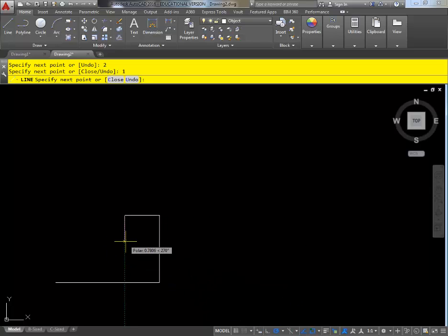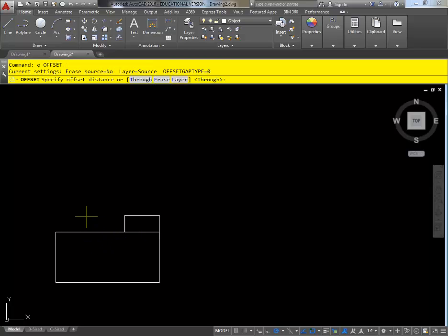And then back down 0.5. Close that. Looks like that should extend. And then I'm going to use an offset of 0.5 to bring that down. So if I'm not mistaken, those 3 rectangular shapes, eventually I'll hit the right button here, are the 3 blue shapes here. So that's my front view.